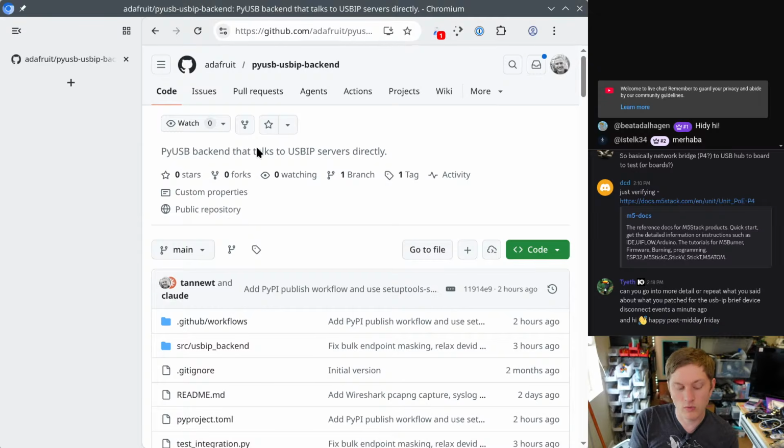And the way that USB hubs work, they don't do enumeration, but they have to convey back to the root hub, like the ESP in this P4 in this case, that a device disappeared and came back, so that the root hub can do the enumeration again. And the way that it does that is that there's kind of 2 bit fields, I think it is, on a USB hub. One says, is there a device on each port of the hub? And then also, did the port status change since you last read the status of the port?